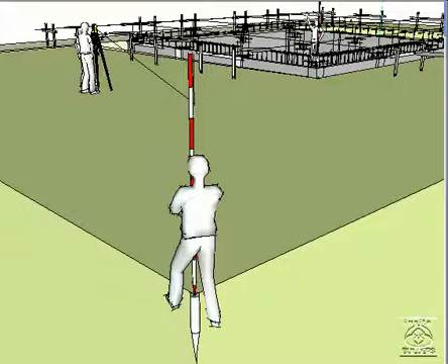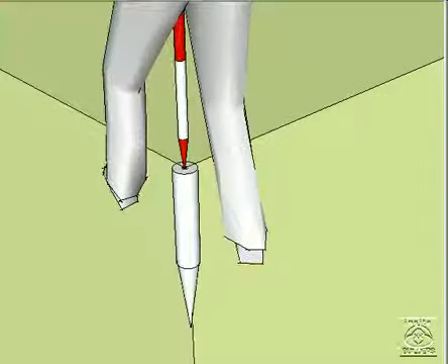The purpose of this short is to show how the string lines are used to set the elevation, or the height above sea level, for the main floor. The layout starts at the reference work point at the corner of the property. Keep in mind that this point both locates the property from a survey monument and marks the known elevation of that work point above sea level.